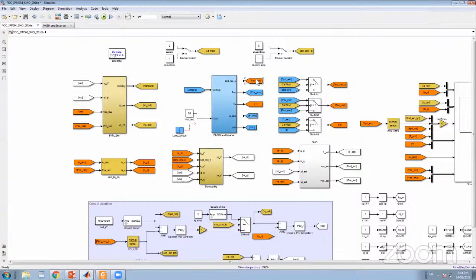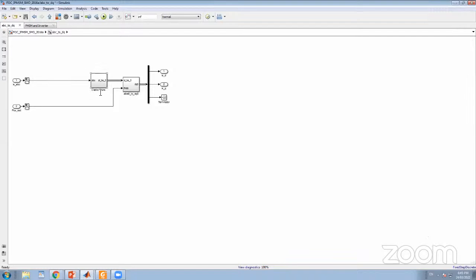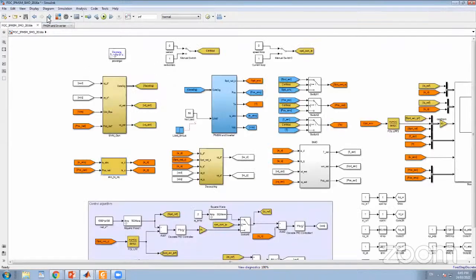So after we get the three-phase current and the position of the rotor from the sensors, the first thing we need to do is normally the ABC to DQ transformation, as you learned from the lecture. Inside this block, it's the Clarke transformation and Park transformation from ABC to DQ. And this is the decoupling module. Professor Data also introduced the decoupling.